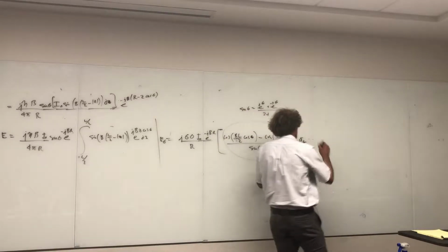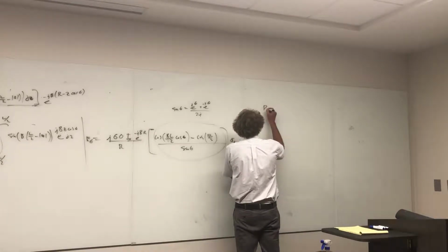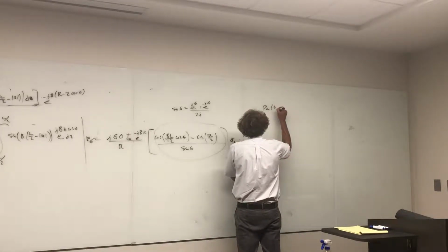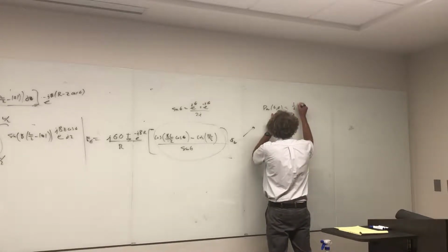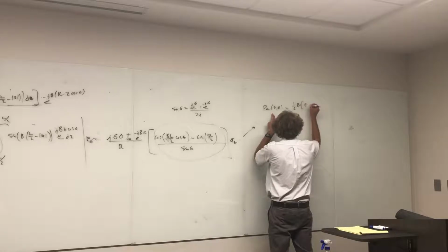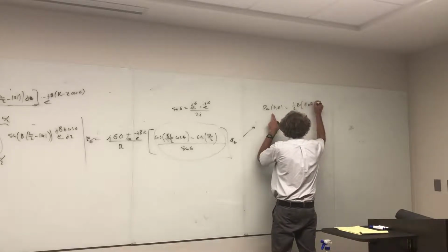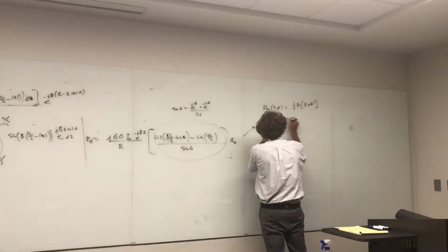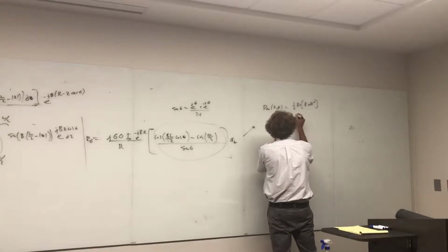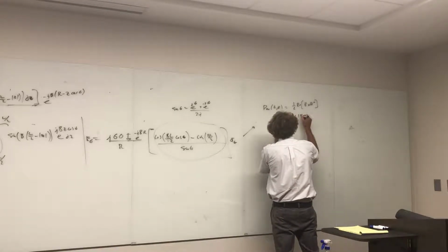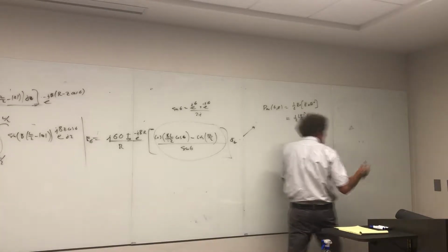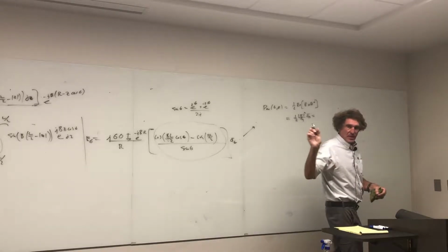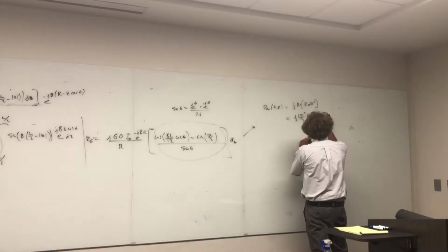Got it, everyone? So what Whitworth does, and hear me, Whitworth does this. When he goes through here and he gets the power density, P Av, as a function of angle and R, technically we should say 1/2 the real part of E crossed H conjugated. But for our cases, because we're assuming free space, we get 1/2 magnitude of the E field squared over eta in the A R direction. And in his book, he's going to have this. Help me out here on the page number. He's going to have 15, and then it's going to be I squared.